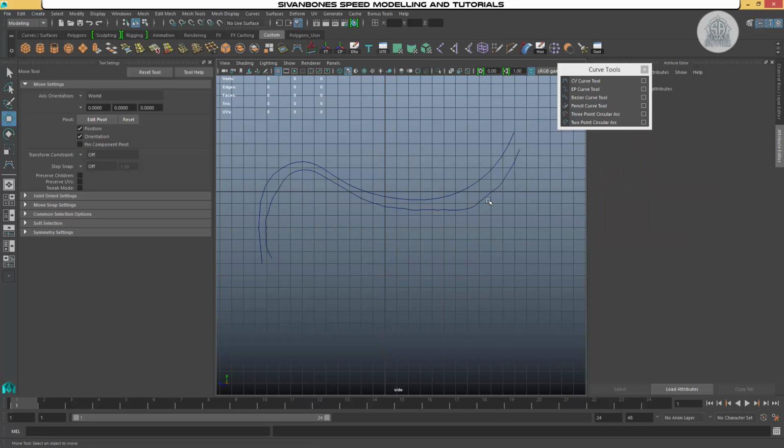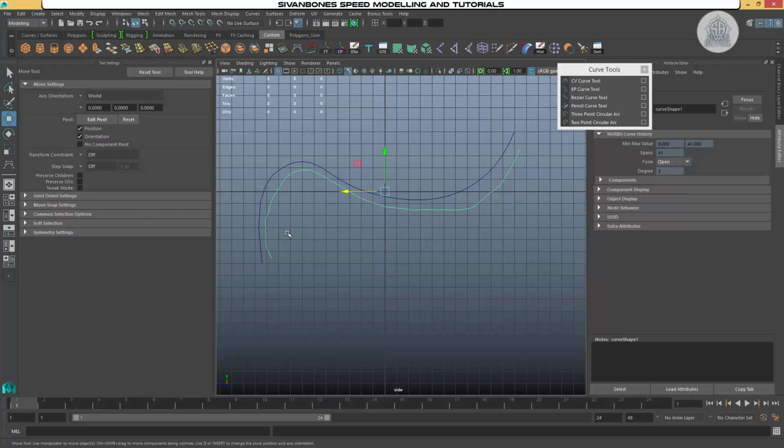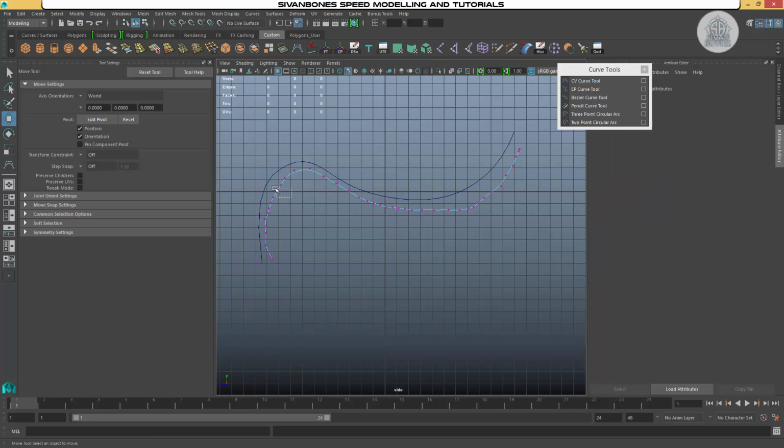So you'll end up, if you use this for a revolve or something like that, it would be very high poly and you would need to fix it after. So they're the two differences. It's good to start with, but then you'd need to go in after and probably tidy it up, by selecting some of the control points and deleting them.